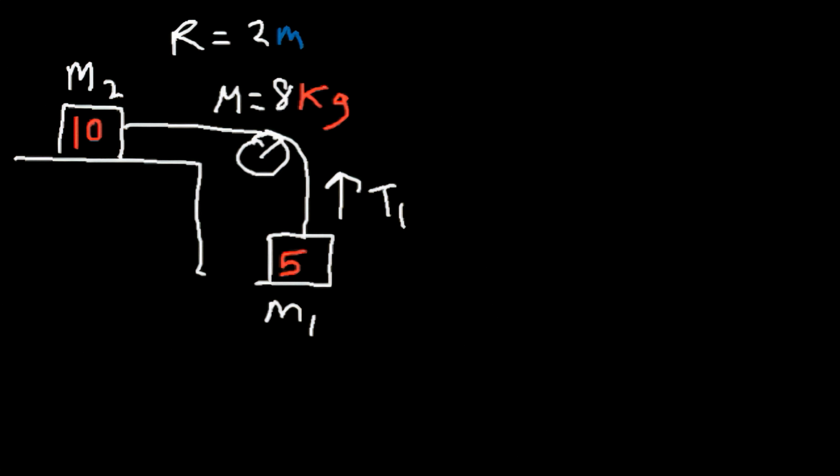Now, that means there's another tension force that's equal and opposite to T1. It's going to be T1, but in the opposite direction. So that is the tension force that accelerates the pulley in the clockwise direction. Now there's another force, T2, that pulls block 2 towards the right, which means that there must be an equal and opposite tension force.